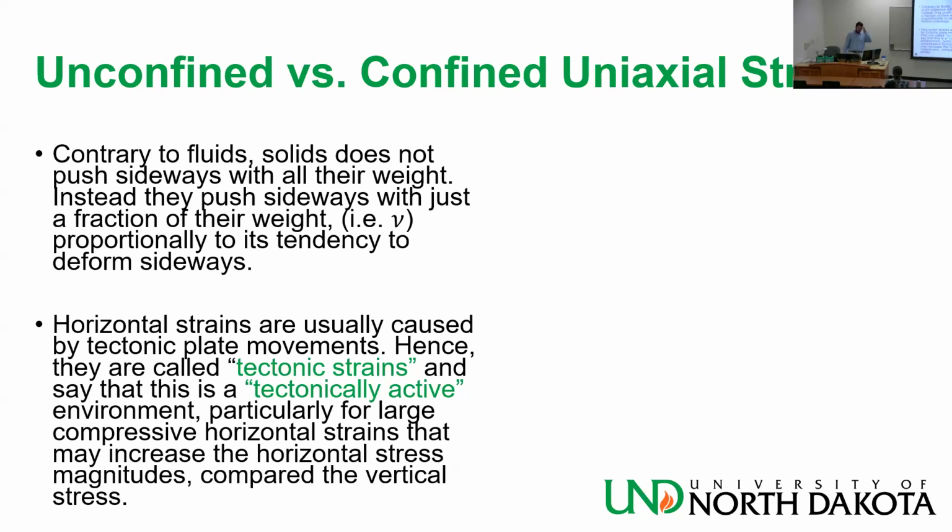Basically, when we say tectonically active, think of strike-slip, reverse faulting. Okay, strong horizontal stresses, strong SH max and SH mean compared to SV. Tectonically relaxed is basically normal.